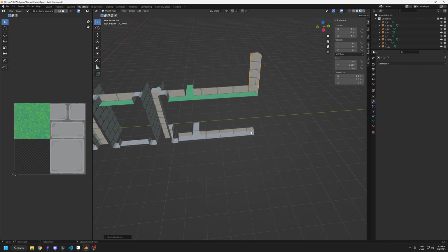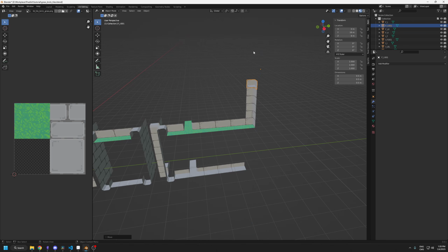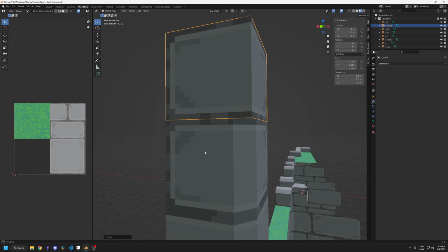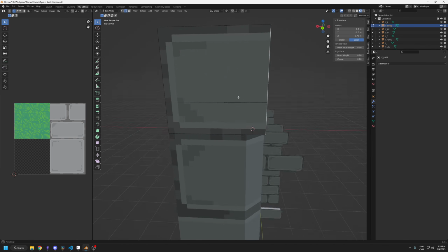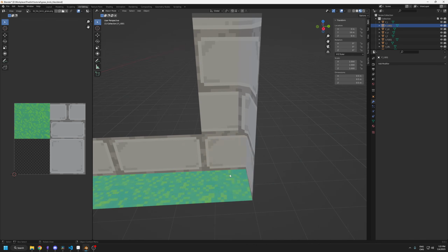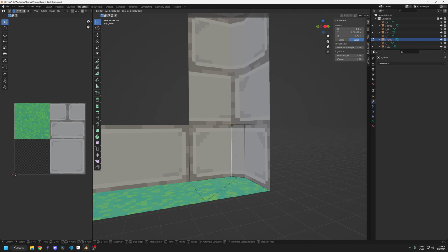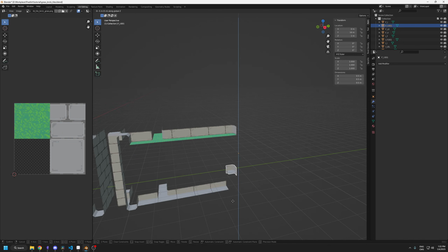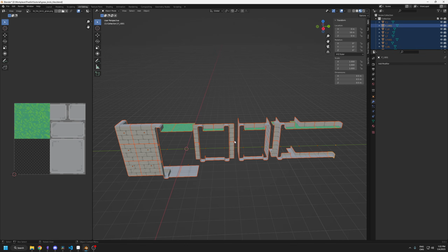If I bring an inner corner, put it on top there, I'll bring the bottom tile on top, and yeah, I'll just need to bevel those ones. So I'll do that approximately. Then I'll snap those to the vertices. Then I'll do the same for the bottom tile. Then I can delete the corner and place my corner back. All right, so that should be all the tiles.